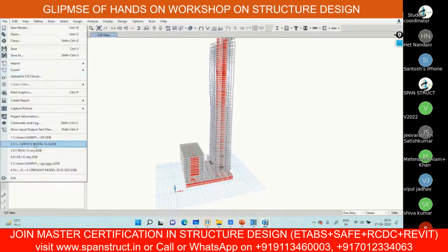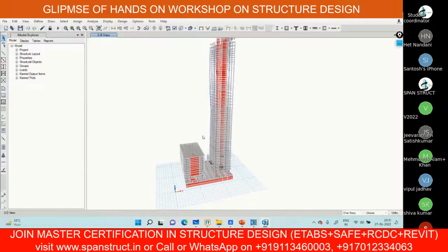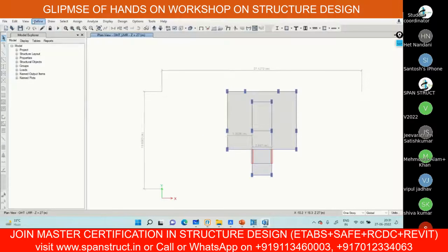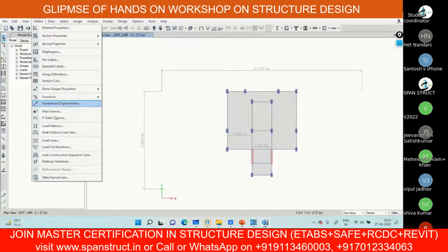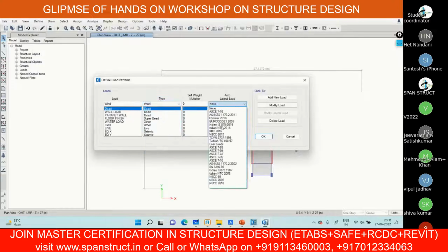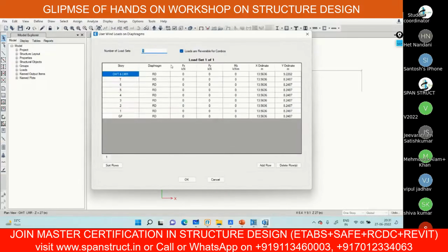So I will open a model here to explain more about what I mean to say here, what actually the diaphragm is. In this project, the diaphragm is applied. When you go to the define option and in the load pattern, when you add a wind here, and select the user load, add new load, and when you modify this, now you can see that you will get a diaphragm here.